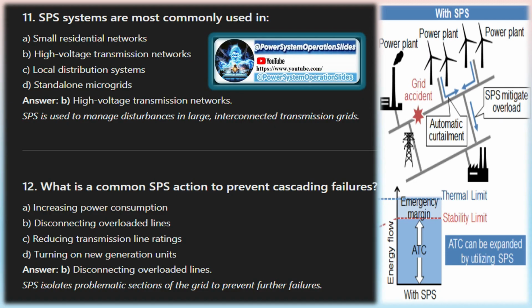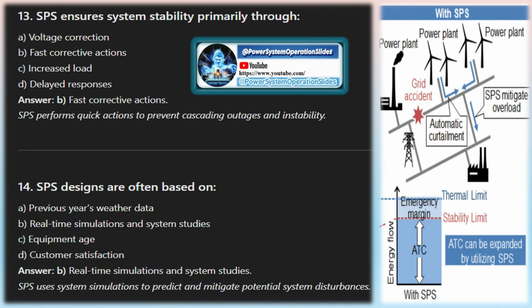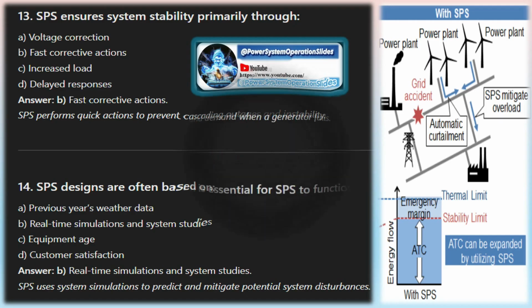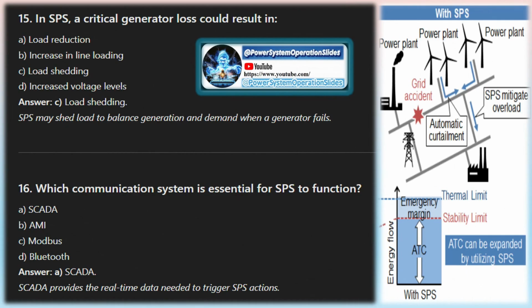Restoration. The restoration plan aims to reduce the duration of power system interruptions as a consequence of blackouts by re-energizing the backbone transmission system as fast as possible, which allows gradual reconnection of generating units and, subsequently, supply to customers. Prompt and effective power system restoration is essential for the minimization of downtime and costs to the utility and its customers, which mount rapidly after a system blackout.